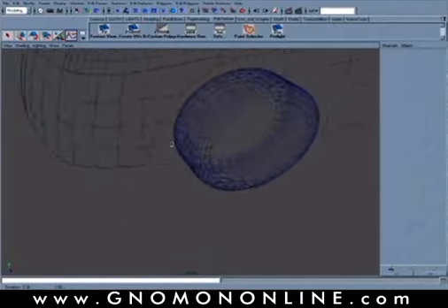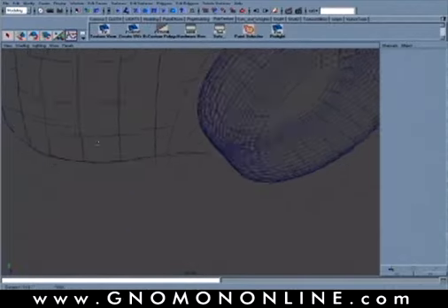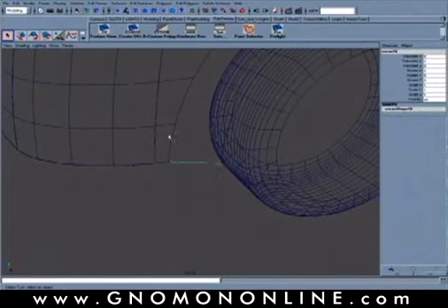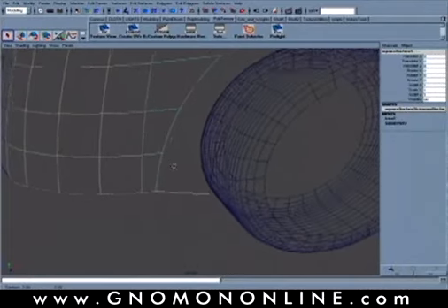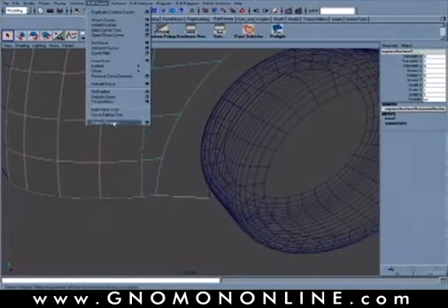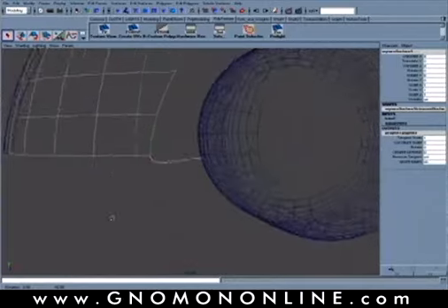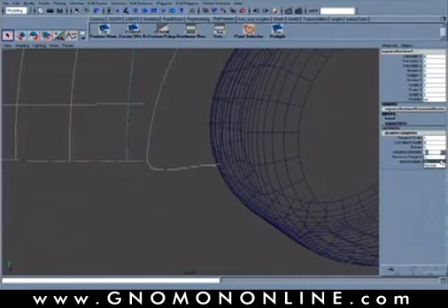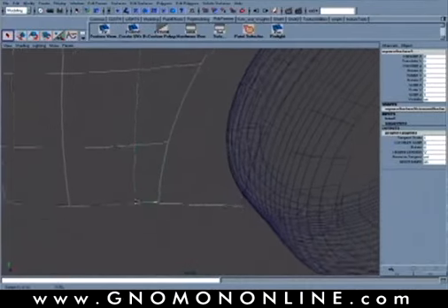Now same idea on the other end to get this smoothly integrated. We will again select our curve and then shift select our surface, and then we'll go in and do the project tangent. And we noticed that again is in the U direction, so I will flip that over to the V direction, and we can see that that's reversed.